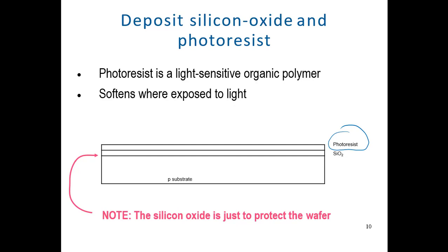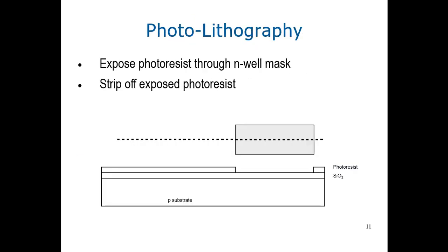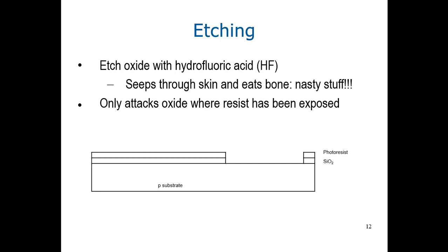And what is the purpose of silicon oxide? It is basically to protect the wafer. And what is the purpose of the photoresist material? It is there to increase the sensitivity of the whole thing to light. Then you are putting your first mask. So this is the mask for N-well. Okay, and what you see is you strip off the photoresist material here, and all the other is the same. So you have applied your first mask and you strip off some region to develop the N-well.